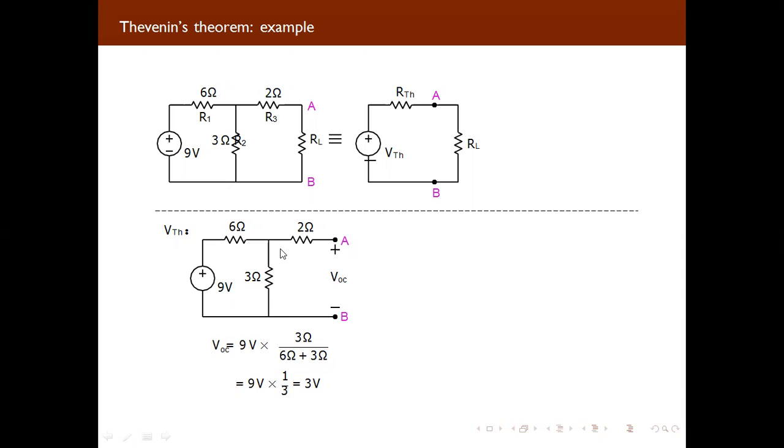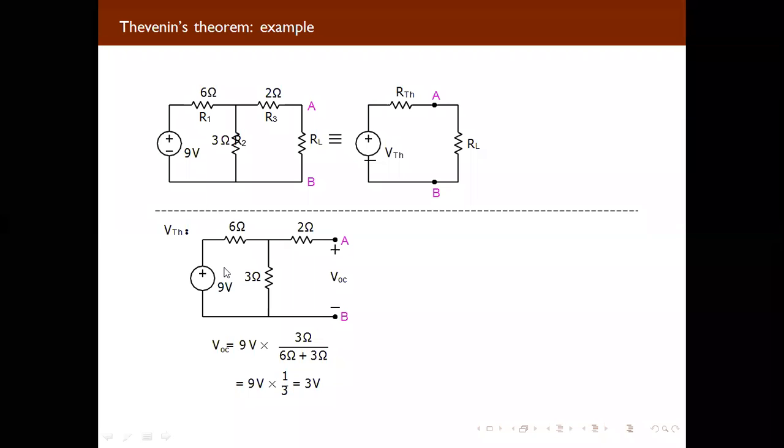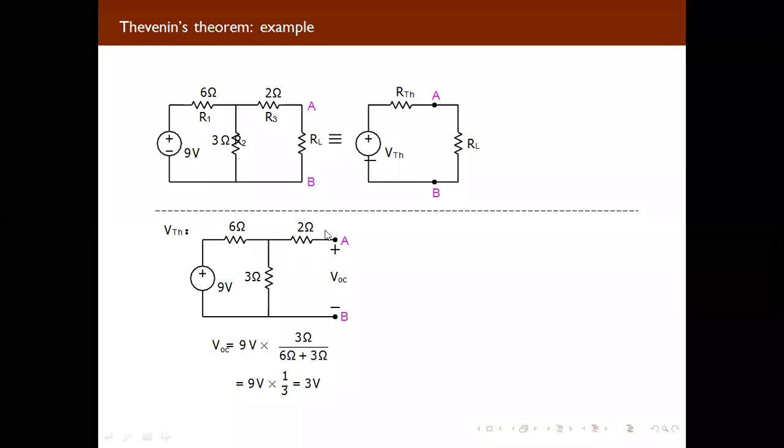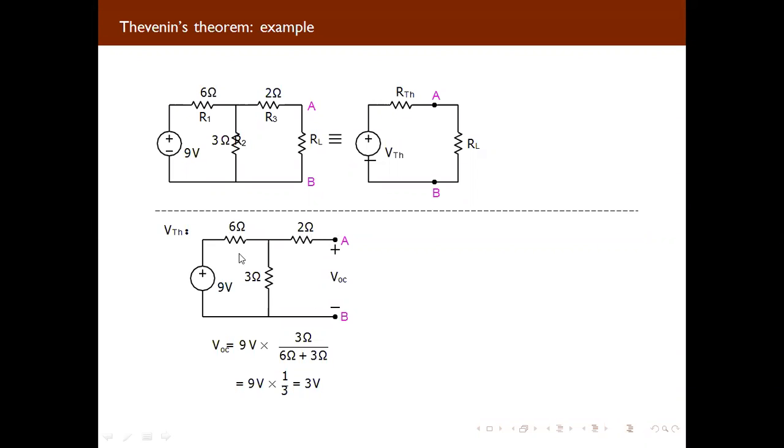So firstly we will calculate this 2 into 3. You can see here, when we consider this as an open circuit AB, and we are supposed to find VOC, we are supposed to find the voltage across 3 ohm. So you can take 3 ohm in the numerator and 3 plus 6 in the denominator. There will be a question: why have we not taken 2 ohm, why are we considering only these 2? Because we are calculating the Thevenin voltage that will be across these 3 ohm, because we are considering this as an open circuit.